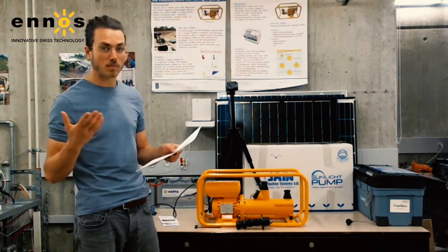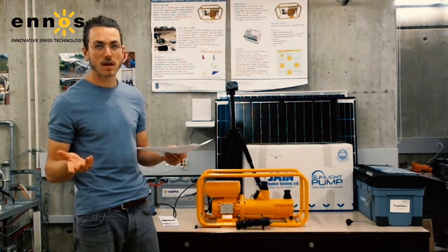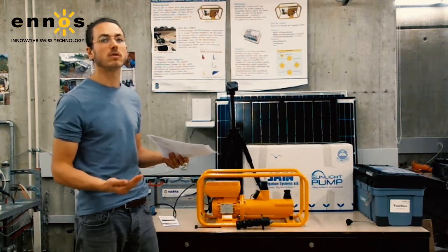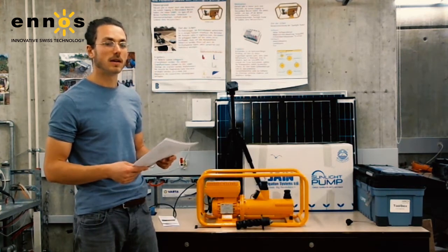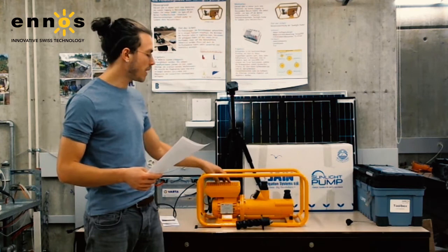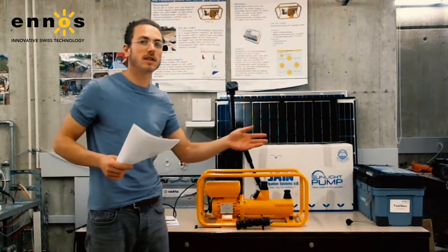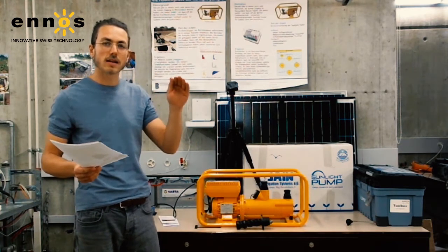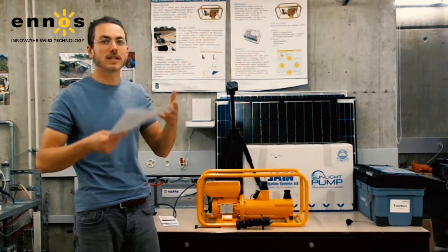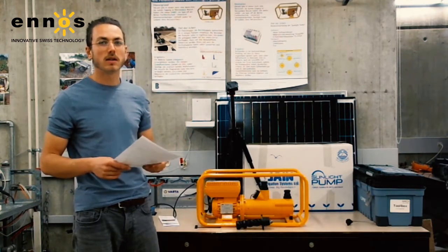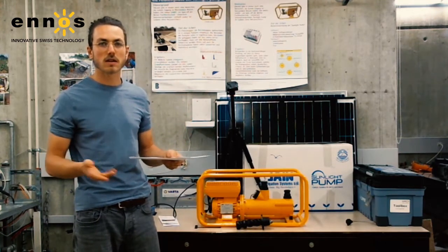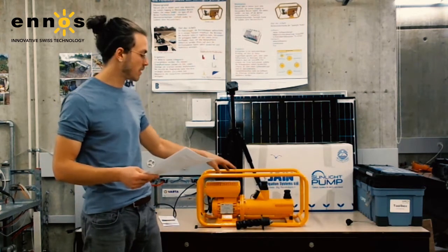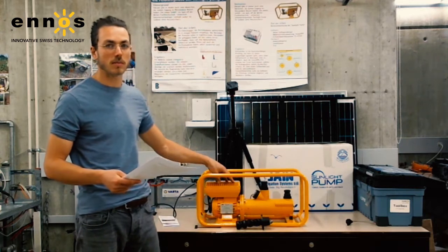Next, we've got our maximum input power, which is at 500 watts. And if we use a panel array with a total of 500 watts, we will be potentially able to pump water a little bit further into the evening, a little bit more in the morning, and potentially when there's mild clouds or a lot of clouds, you'll be able to get a little bit more out of your system. But under optimal conditions with lots of sun, you will not necessarily require a total of 500 watts to get the maximum water flow out of your pump.